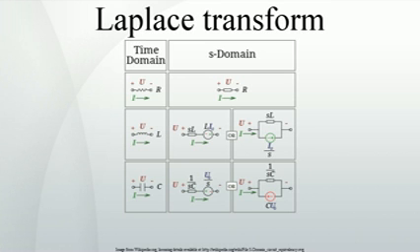The unilateral Laplace transform takes as input a function whose time domain is the non-negative reals, which is why all of the time domain functions in the table below are multiples of the Heaviside step function, u(t). The entries of the table that involve a time delay τ are required to be causal, meaning that τ is greater than 0. A causal system is a system where the impulse response h(t) is 0 for all time t prior to t equals 0. In general, the region of convergence for causal systems is not the same as that of anticausal systems.